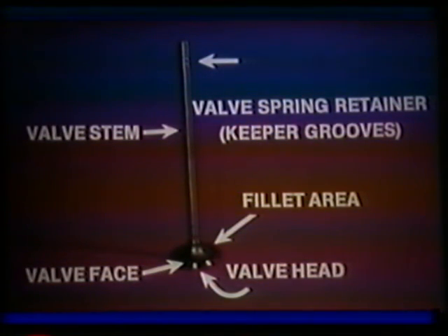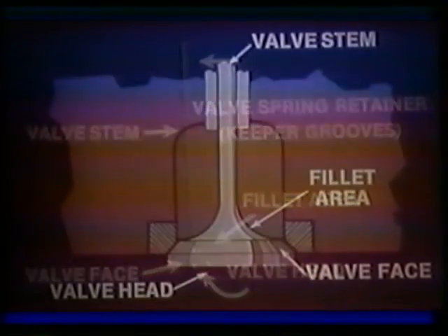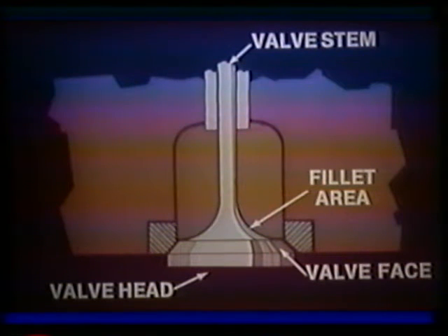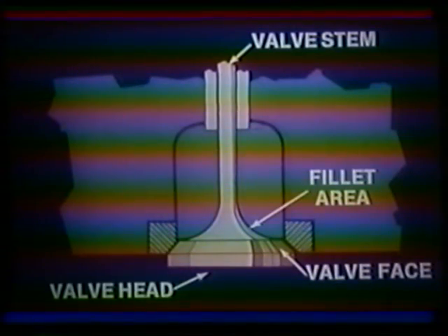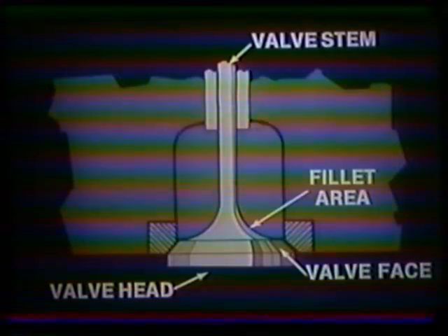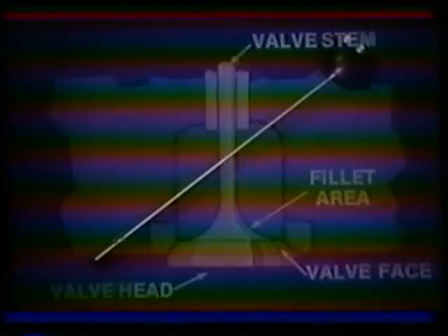When the valve is closed, the face seals the combustion chamber by making contact with the valve seat in the cylinder head. The seat is also ground to a fine finish. On some engines, the valve seats are replaceable inserts. The 3200 series cylinder heads have no intake valve seat insert, but they can be adapted to accept them at overhaul. Thus, we need to manufacture a valve that will do a good job of sealing and venting our cylinders at various points in the combustion cycle.